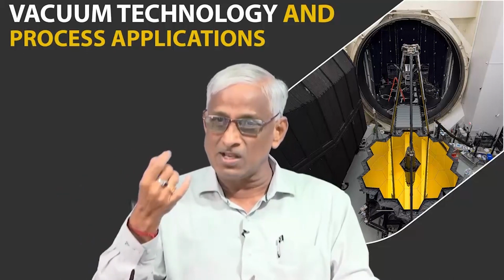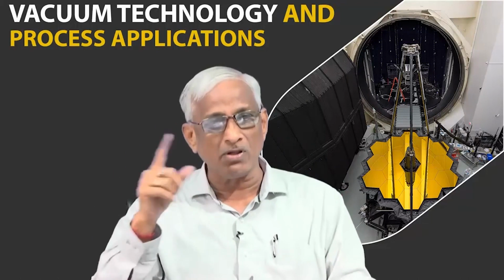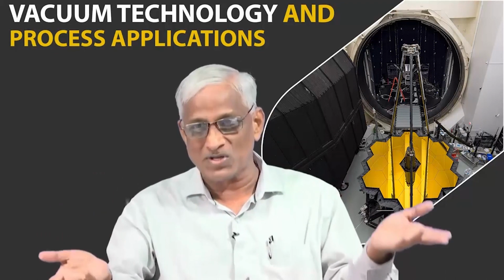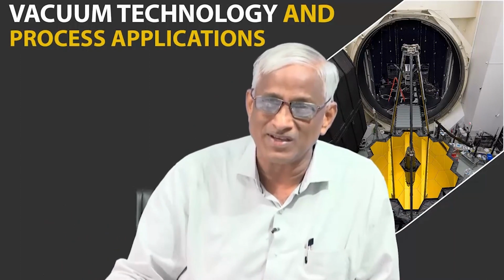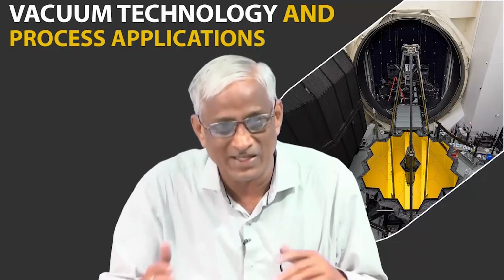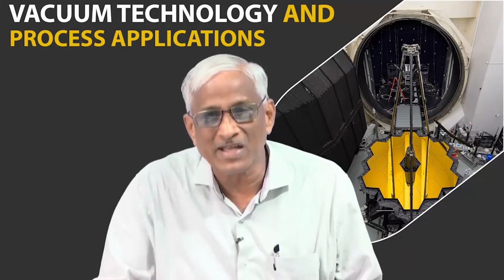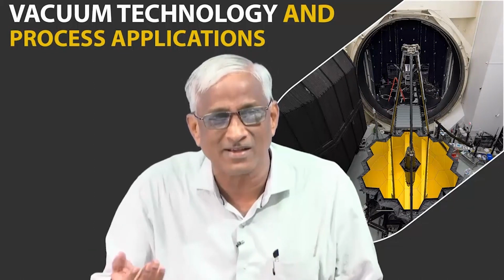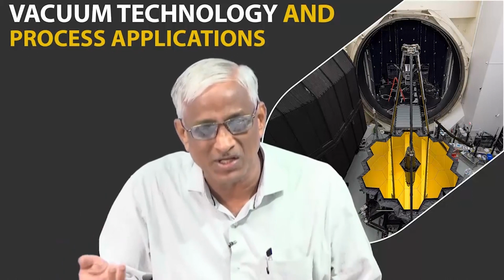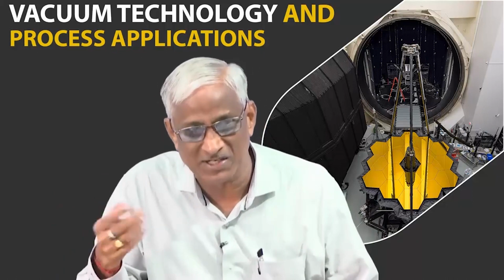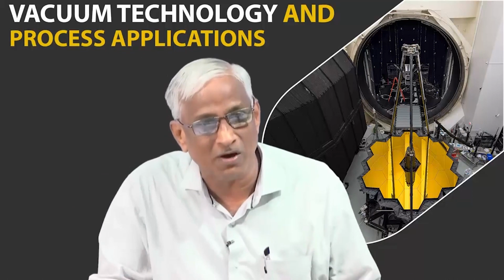So, vacuum technology plays a very important role through high quality fabrication techniques based on some standard equipment available, based on some standard designs to minimize wall thickness, etc. You have to keep track of all these issues. Well, instead of talking about welding and brazing, why am I talking like this? Because these welding and brazing things you can get easily from any book, even routine mechanical engineers do them, nothing great we are doing separately for it, excepting that some specialized things are there like electron beam welding and plasma welding, which are not normally used unless it is a very fine welding on the high pressure side. But on the vacuum side we use all sorts of advanced welding techniques.